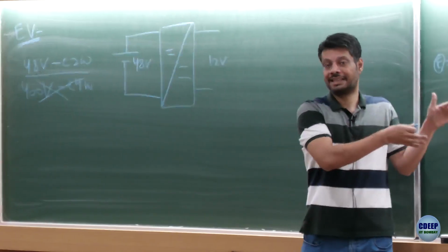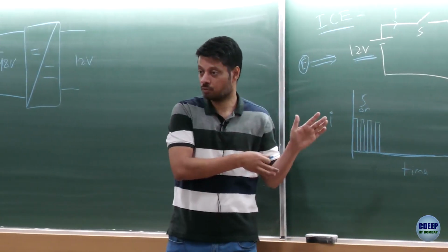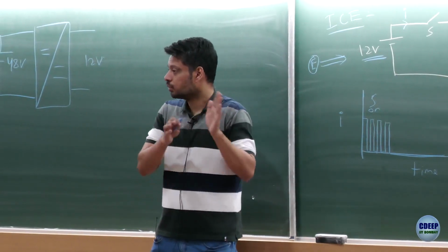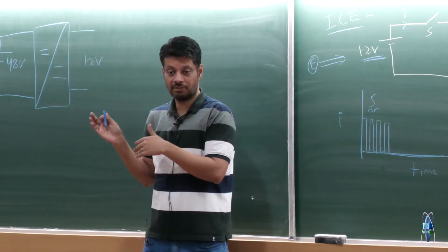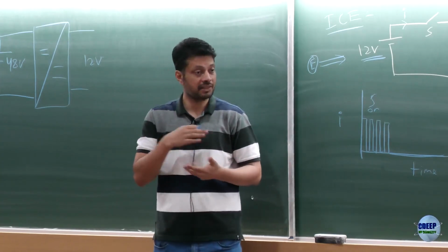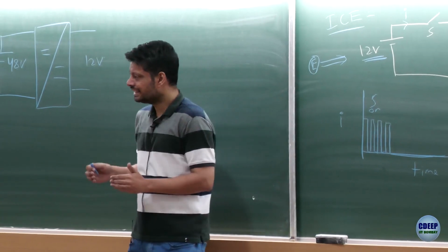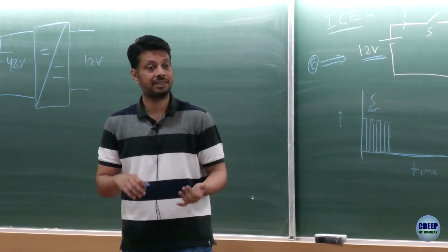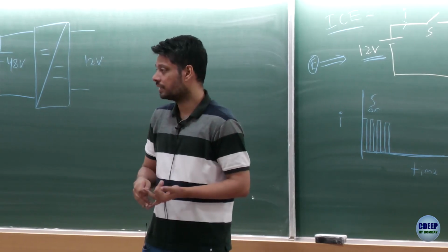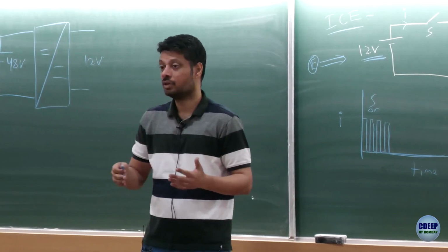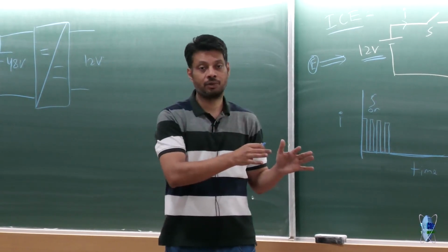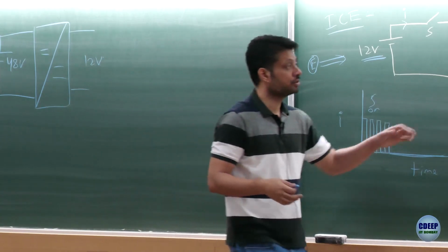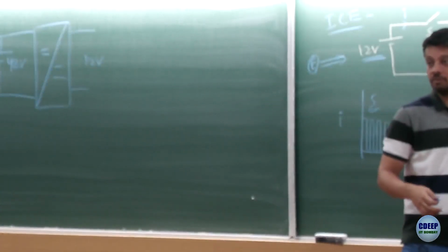So a system which is set in, right, which is this 12 volt system for automotive, makes all of these components enormously cheap and reliable. You want to shift to a 48 volt system in the vehicle where your horn, your light, your fan, everything works on 48 volt. It's not an engineering challenge, right? You can do it. As an engineer, we can design it, we can make it, but the challenge is making it cost effective, right? You have to gain sufficient volumes. All the vehicles should shift to 48 volt. Only one manufacturer shifting to 48 volt, the person may not be able to source reasonably cost horns of 48 volt and so on.